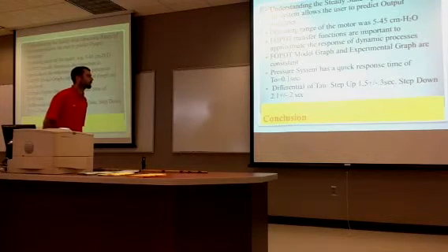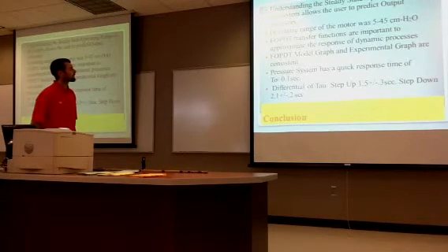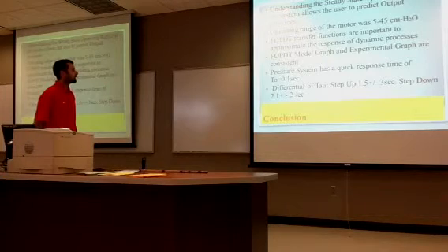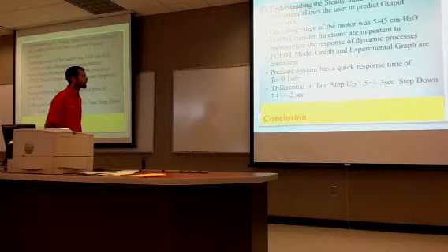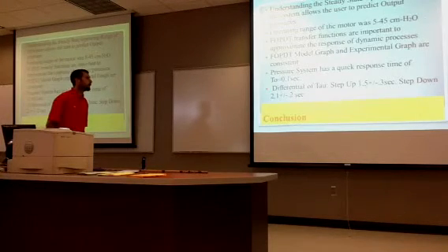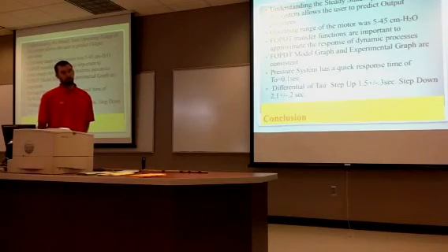On the pressure system, we had a quick response time of 0.1 seconds on our T-naught, and we did have a differential in our tau. On the step up, it was 1.5, and on the step down, it was 2.1, which showed that it had a delay in its response.